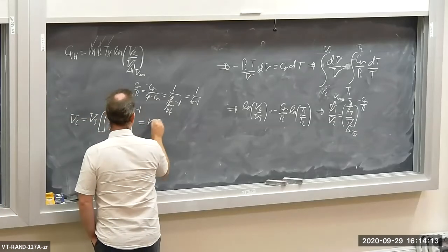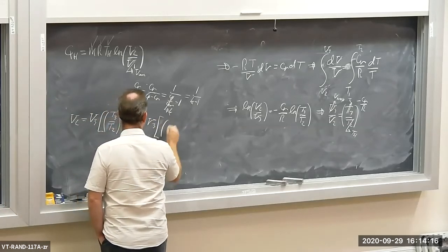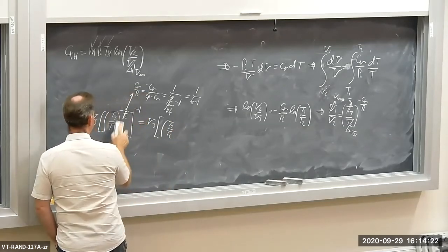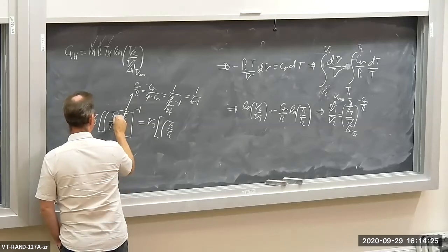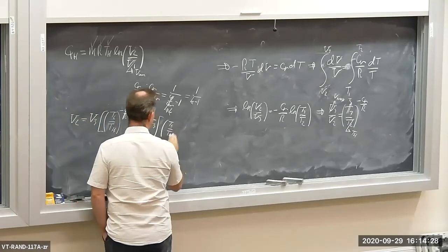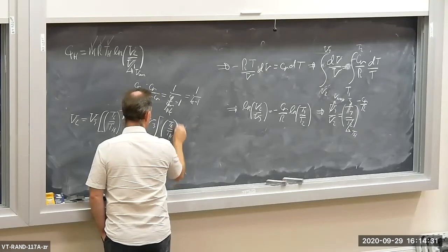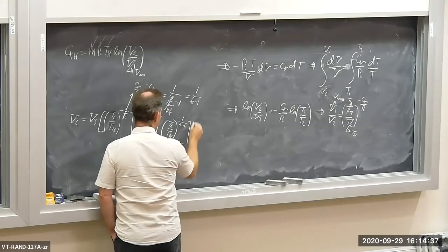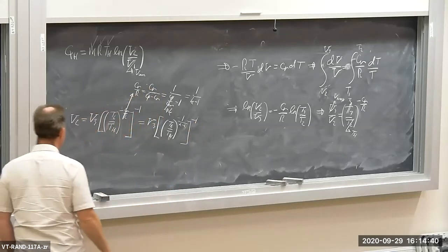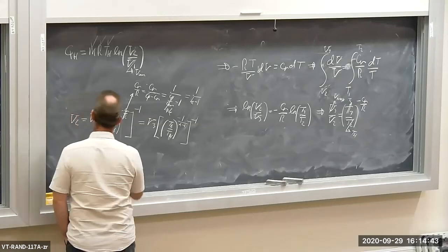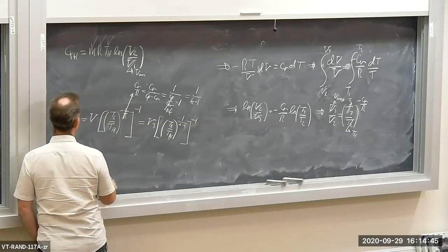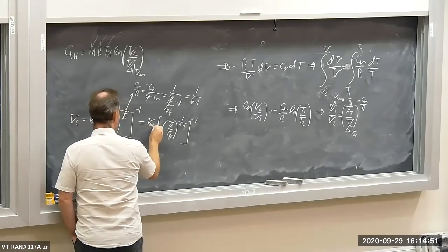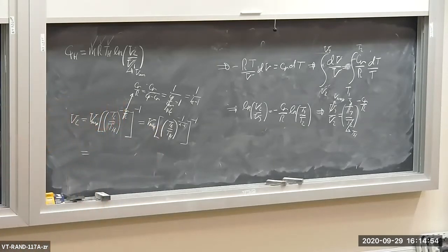So V2 equals V3 times (T low over T high) to the minus 1 over K minus 1 power. Let me plug in. Oh, and remember V3 is V max.